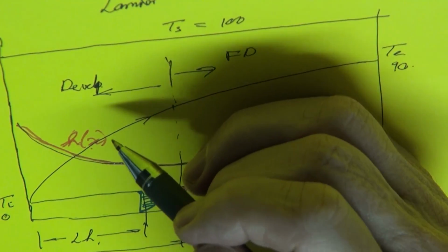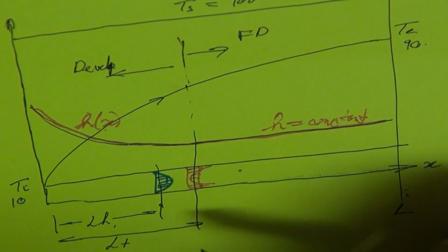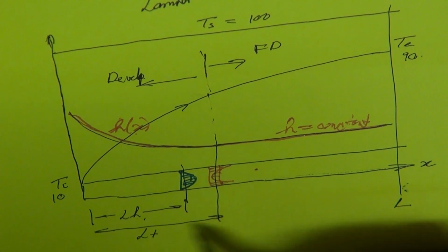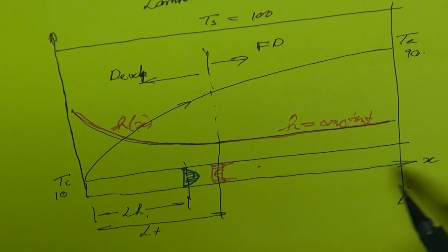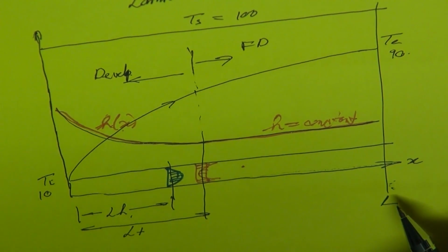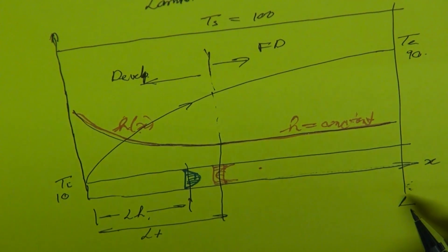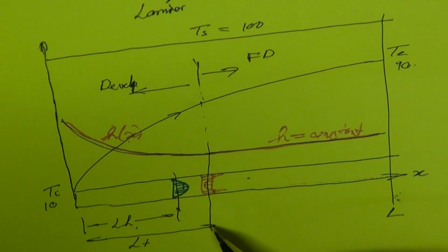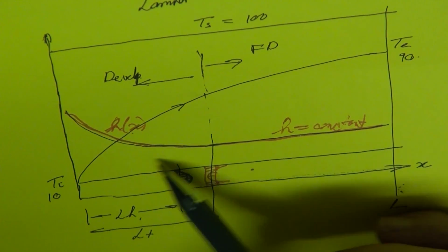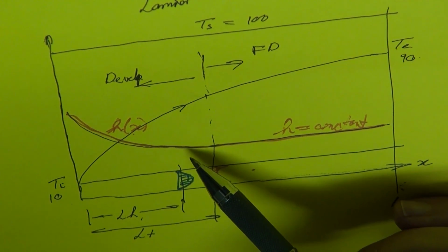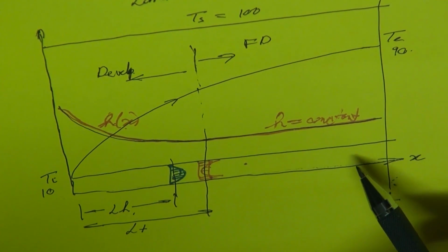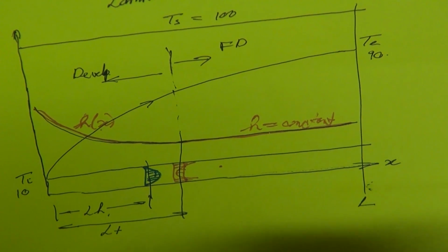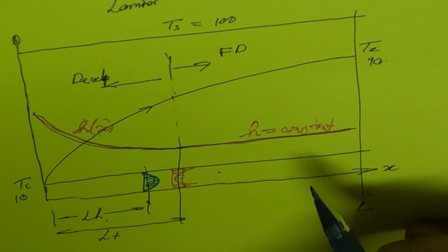Okay. Now what have we determined from our calculations? We've determined from our calculations that the flow is laminar, and therefore we've calculated these distances, but we do not know what this total length is. So if the total length is going to be smaller than about 13 meters, 12 to 13 meters, it means that most of the flow is going to be developing. However, if the total length is maybe going to be 1,000 meters, then this distance in comparison with the total length is going to be small.